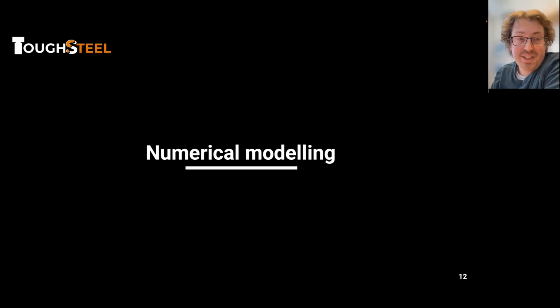But to trust the results in the simulations, model validation is necessary. And this stereo camera setup offers further options. I will just show the modeling procedure here for a finite element analysis as we usually do it of the crash box, and then compare the simulation with the stereo DIC. So this is a procedure in general, not really coupled to a specific material, but the steel material is used here.